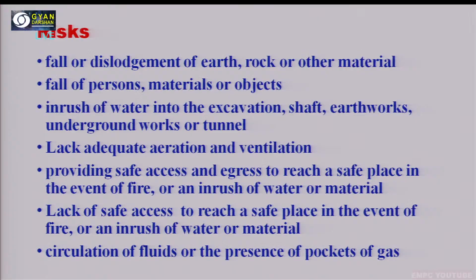Third, if a shallow water table is met, then there may be an inrush of water or other liquids into that cut or the tunnel. If such water inrush happens into the excavation, shaft or other underground earthworks or tunnel, the workers may get trapped there, and it may cause a very large risk to their life. Even in that case, there may be some injuries, and there may be a threat to life also.